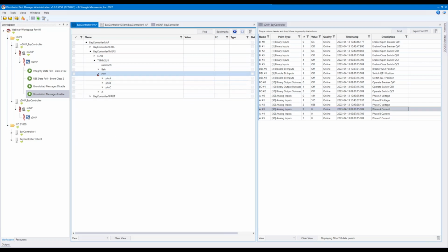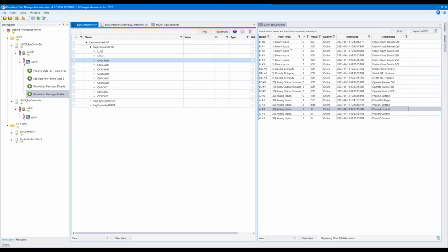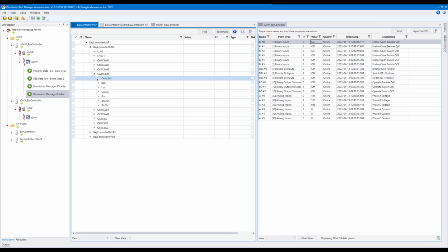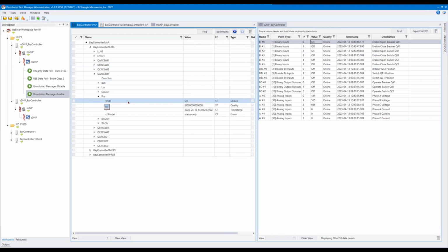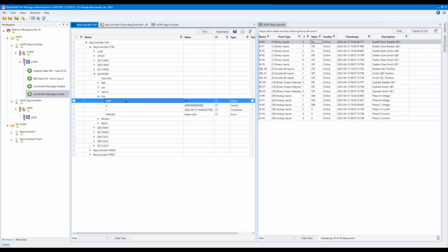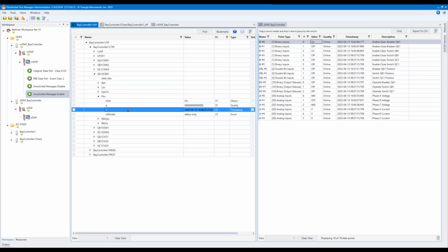Now, one thing that I do want to point out before we move on, we talked about in DNP3 how metadata is associated with a payload. Effectively, this on value that we have for the binary input has a quality and timestamp that are associated with it. As Christoph mentioned, things are a little bit different in 61850. If I go back to that position value that we looked at earlier for our breaker, we'll see that we have an stVal, and then below it we have a q, which stands for quality, and then a t, which is our timestamp. Now, from a data object level, which is what we have here at position, these three are all together. But I could address just one of these data attributes, for example, the Pos.stVal or the position of the breaker individually, and send that or read that in a message and not necessarily receive the quality and a timestamp. A small distinction, but we'll see where that comes into play here in just a moment.